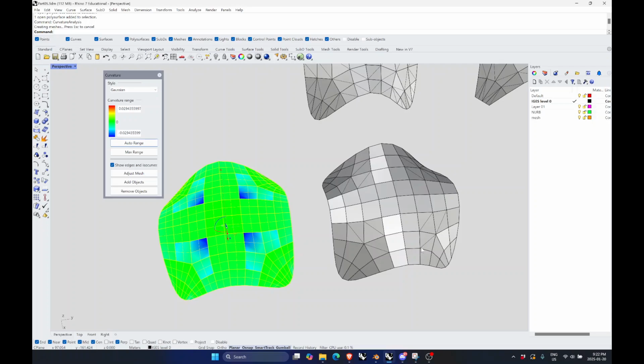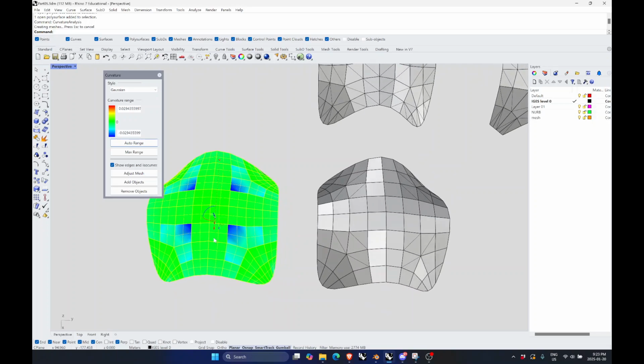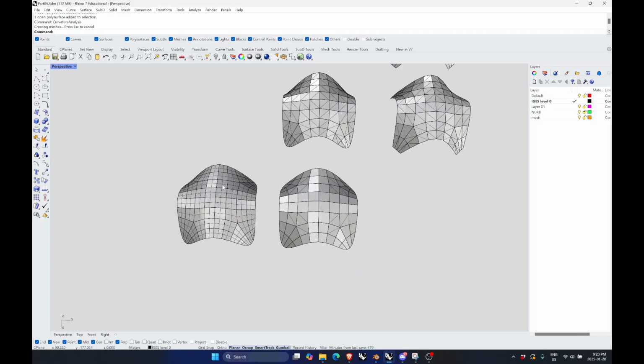So the ones that have some curvature, let's do those. The ones that are minimal curvature or totally flat, I don't want to triangulate. So you can see how it picked the blue ones on the left side to triangulate on the right side. Okay, so this is good. There's a bit of a comparison here, but I could only run the curvature analysis on the NURBS.